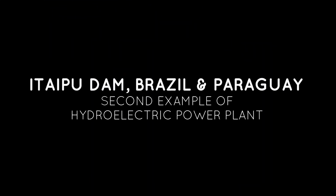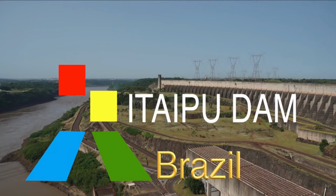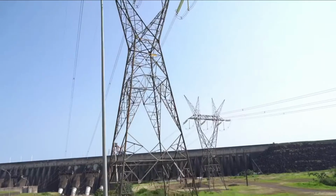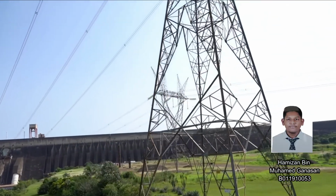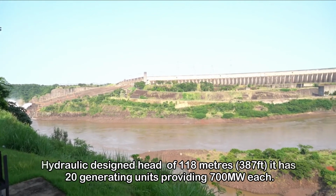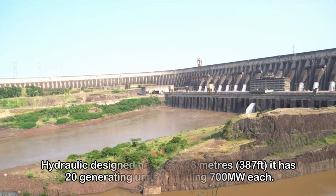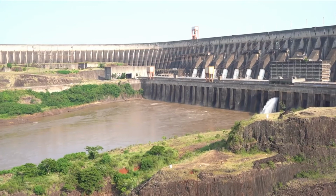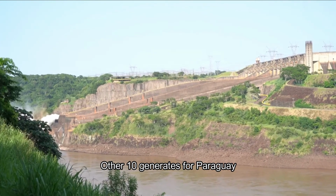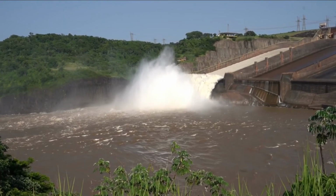The second example of a hydroelectric power plant is the Itaipu Dam, which is located between Brazil and Paraguay. This dam is the second most electricity producing hydroelectric power plant in the world, surpassed only by the Three Gorges Dam. The total capacity of this dam is 14 gigawatts. With a hydraulic design height of 180 meters, which is 387 feet, it has a total of 20 power generating units providing 700 megawatts each. Among these 20 units, 10 units generate power for Brazil, while the other 10 generate power for Paraguay. Among these 20 generating units, only 18 are usually used and 2 are kept in reserve.